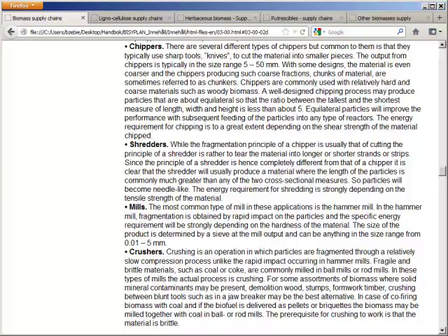A chipper using sharp tools will be very sensitive to any contaminants like stones coming in with the material. Since the chipper aims to cut the material, it will be a combination of cutting and shearing that disintegrates the material, and the energy requirement for comminution in a chipper will depend to a great extent on the shear strength of the material chipped.